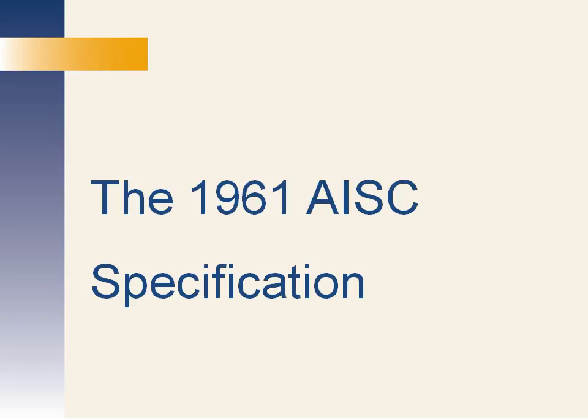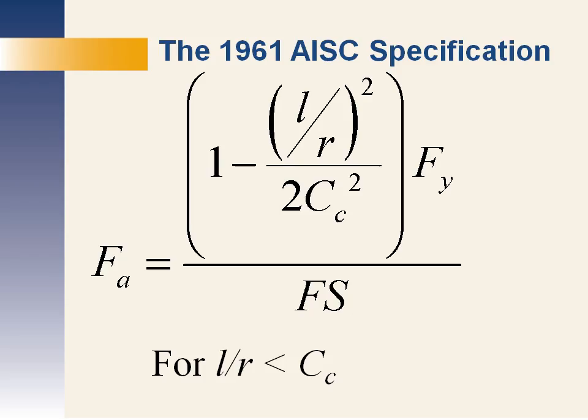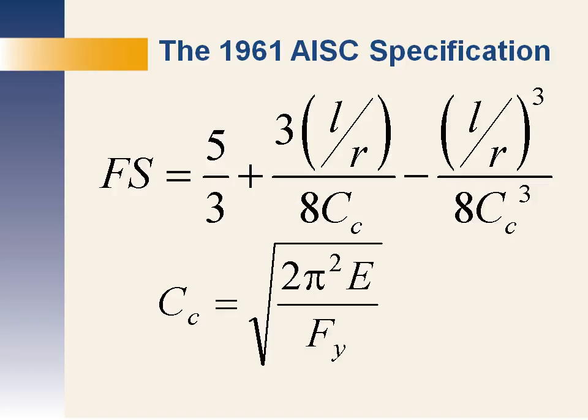There was a 1961 AISC specification. It has the distinction of being the only AISC specification that was not written into an AISC steel construction manual. This was in spite of many landmark improvements that were made in it. In fact, you can see the start of the modern formulation of inelastic buckling here from that specification. Note also that Fy was now a variable in the equation. This is the era in which it began that multiple grades of steel could be chosen.